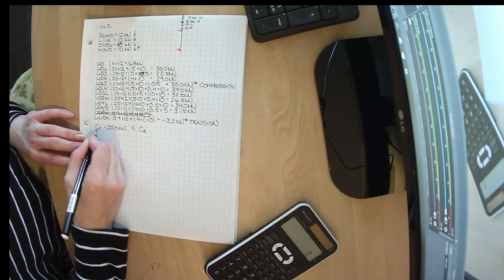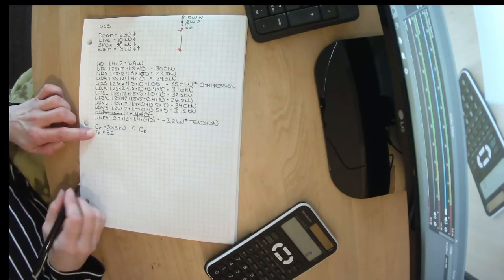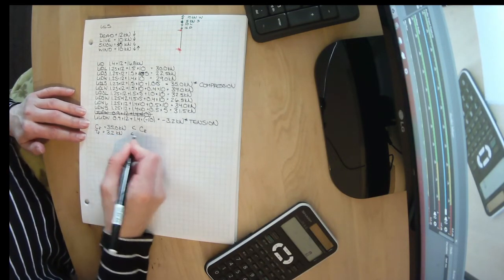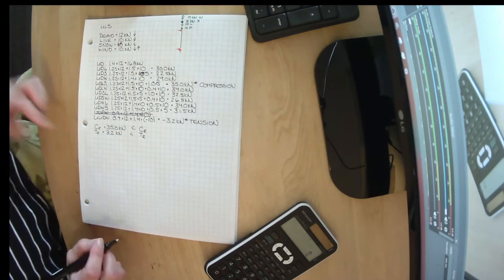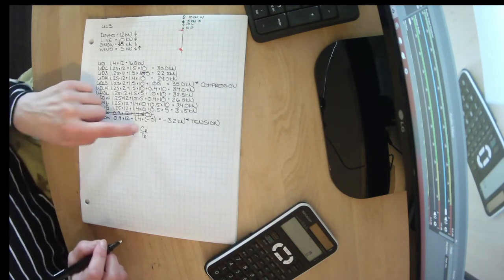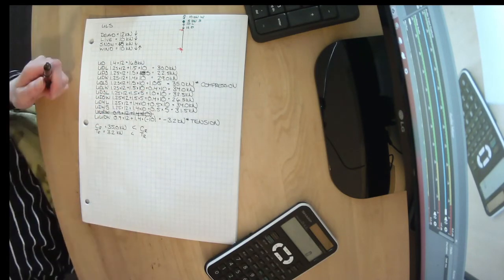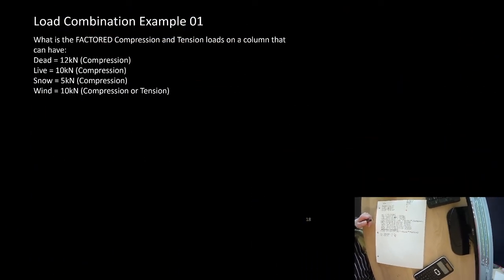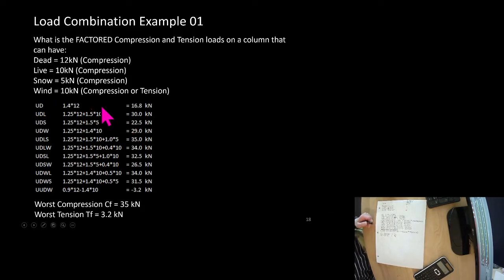And we need our factored tensile load. Now, I'm writing T here. That means I know it's going in the other direction. It needs to be less than our reduced capacity for tension. And we will figure out how to do those calculations next term. And we need both of these things to be true to make sure this column is strong enough. So that was our first load combination example. We have another one. So you can see all of that worked out here.